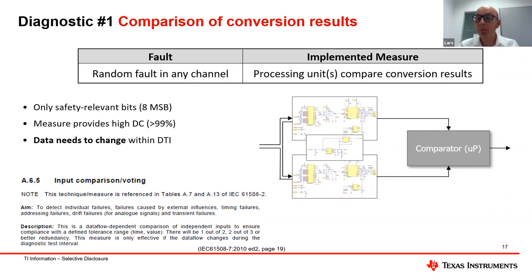And you can also see this, what I forgot to mention before. You see also the stacking of the 2 channels. So the current for the 20 milliampere loop comes in here, goes up, goes through the shunt, goes down here to the second one, and goes back to ground also. And here you can see that the current of both channels is the same, basically.